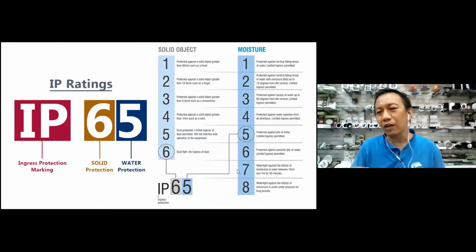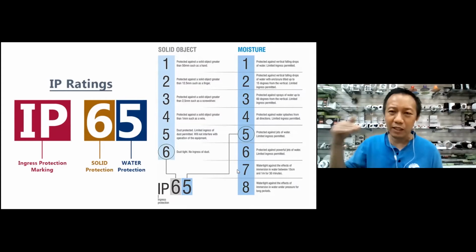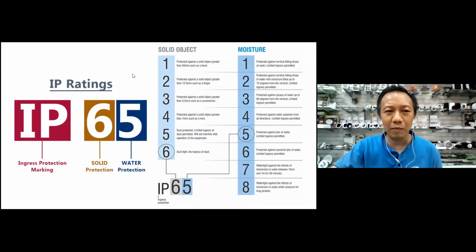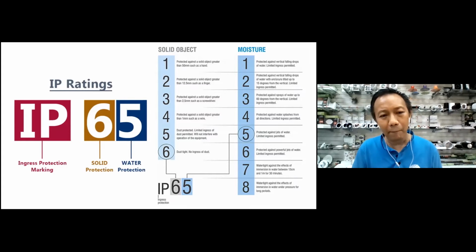Okay, lastly, you have to also consider yung IP rating. Ano ba yung IP rating? Ingress protection. Ingress meaning in, di ba? And then may numbers, dalawang numbers ka makikita. So yung first number refers to yung ingress protection for solid objects. And then yung last number is yung ingress protection for water.